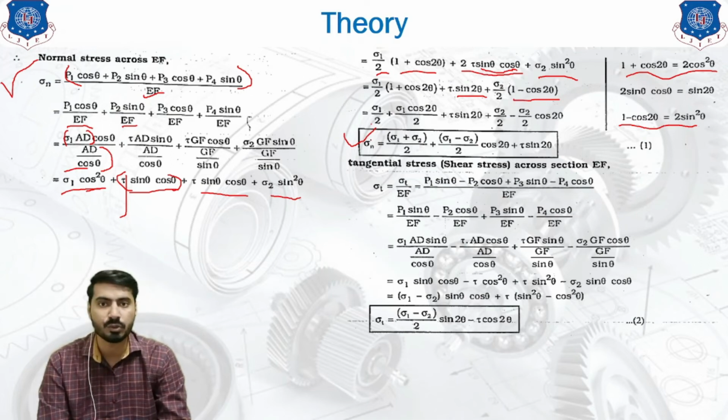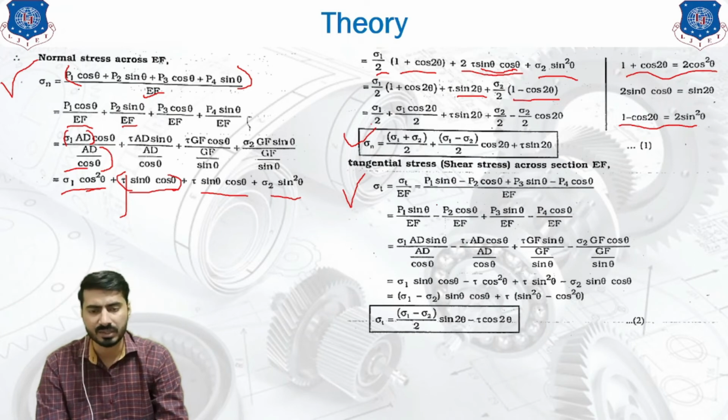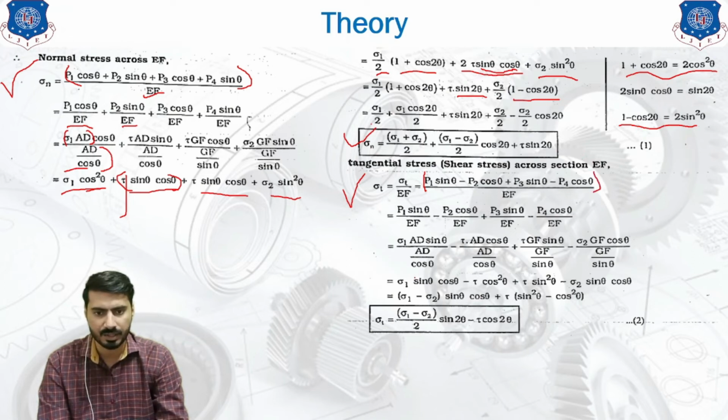Similarly, we are going to derive the equation for the tangential stress. For the tangential stress, we are going to use the same formula, force upon area, but instead of the normal force, we are going to use the tangential force. Similarly, if we use the same trigonometry formula and simplify it, then our tangential stress would look like this.